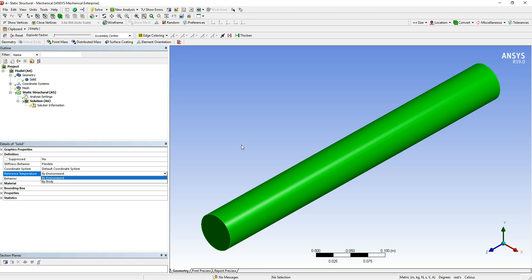Now, if we go by environment, we're essentially saying that we're more considering how this thing is going to dynamically affect the rest of it. But because we have a bar, we're not too fussed. We can stay by environment because we're going to fix one end, and we are basically going to hit it. We're going to hang, I don't know, let's go something daft. Let's go 800 newtons. We're going to hang 800 newtons straight off the bar and look at the effects of what it causes.